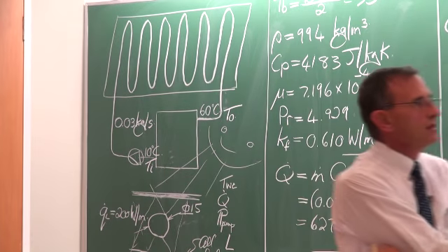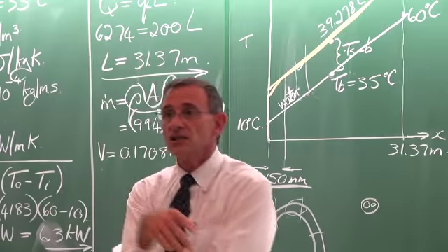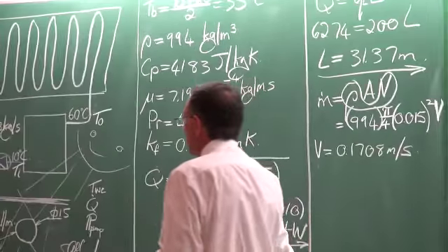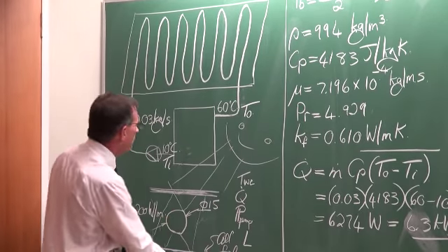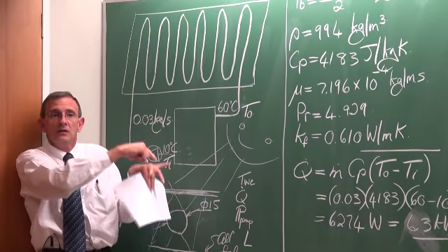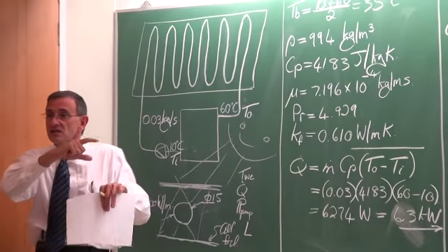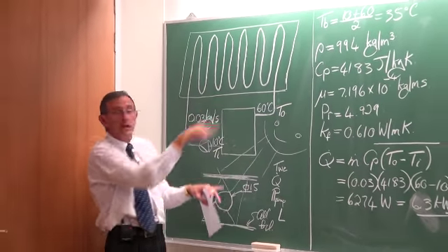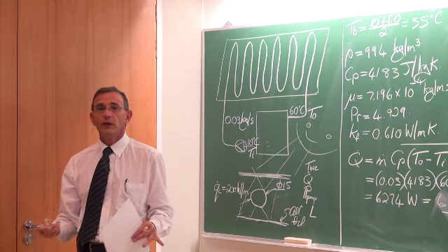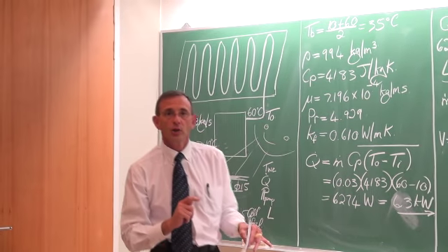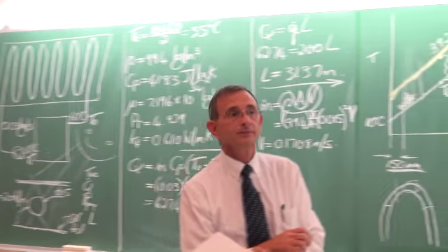But because the power requirement in any case is so small, in many cases, if you design it correctly, you actually do not need the pump. Just by the temperature differences, this thing will circulate itself if it is correctly designed, and you can get away without the pump. Okay? Any questions?